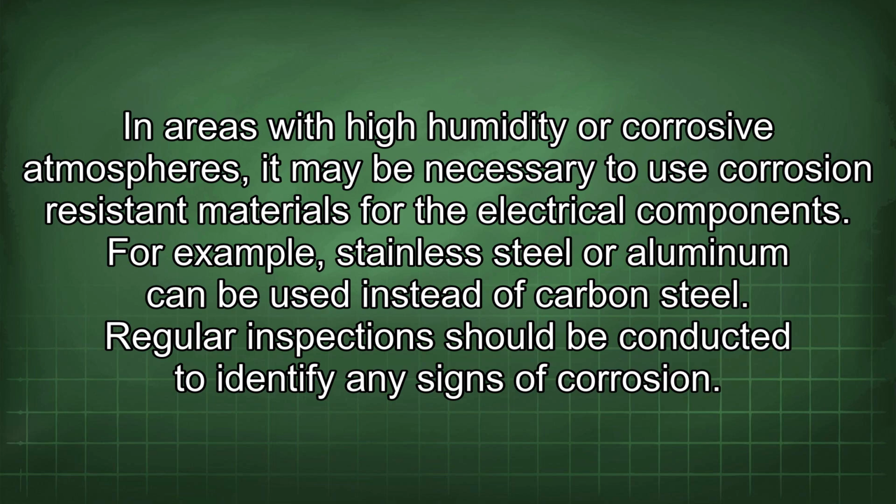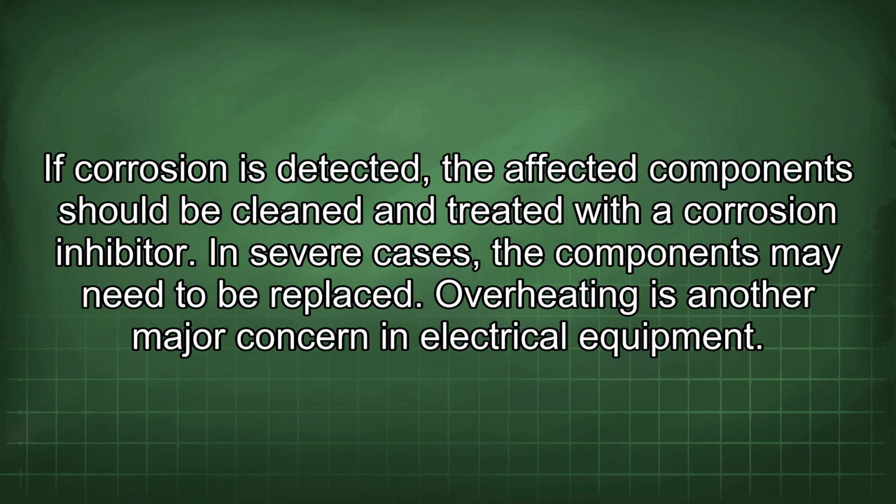Regular inspections should be conducted to identify any signs of corrosion. If corrosion is detected, the affected component should be cleaned and treated with a corrosion inhibitor. In severe cases, the components may need to be replaced.